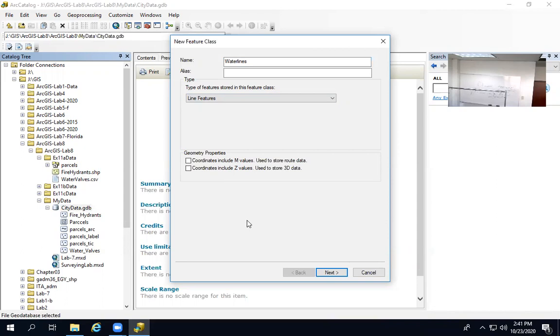If you're like me, stuck in transportation, sometimes you want to add something called M values. M values are measurement values. For your lines, you want to add measurement. I'm not going to do it right now, but if later on you're working on a bus line or a road and you want to add the measurements, you add this M also. If you're doing some topographic mapping with Z's, you want to add a Z value as well. Same thing. Everything you do here is going to add to your new layer or your new data file.